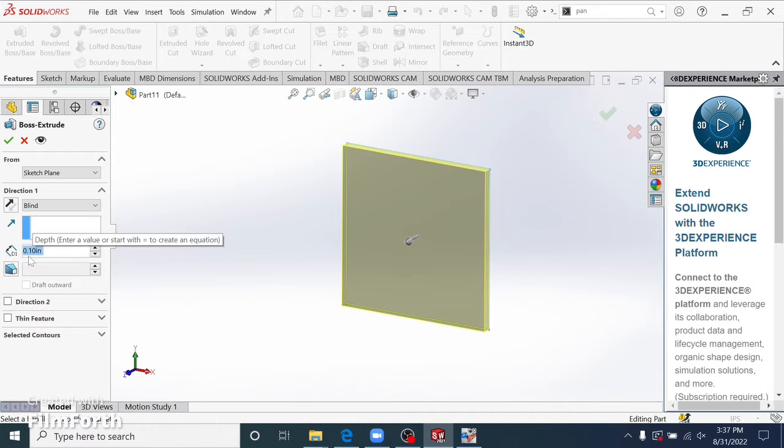So just in case if it has an error saying that it cannot select a sketch, you just exit out, click that one on the side menu on your sketches, and then click on Extrude and you're good to go. Okay, and we choose about 2 inches or 2.5. Oops, I forgot what it was again.